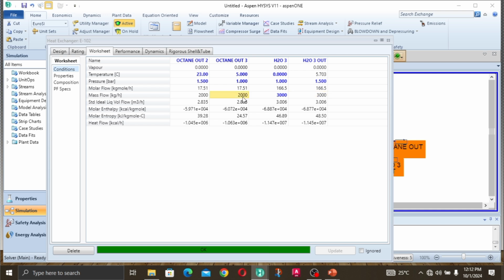The mass flow rate for Basaka's bowl currently is 2,000 kilogram per hour, and Mary is having 3,000 kilogram per hour for this third bowl. So it means the quantity of frozen soup is greater than the quantity Basaka is currently having right now. With that, we expect that the heat transfer would be more efficient. And we currently do not have a temperature cross, but let's try and make this 4 instead.